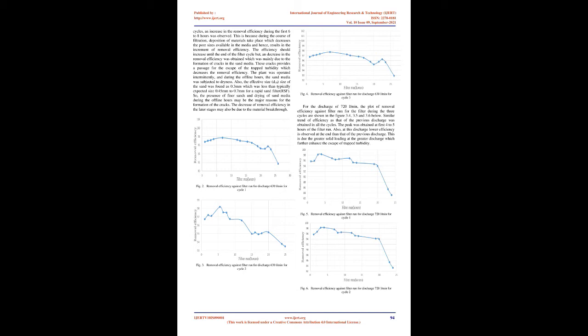Flocculator. A baffled type hydraulic mixing flocculator has been used. At the beginning of the flocculator, a separate chamber for the mixing of alum is provided. As the coagulant is added to the water, the colloidal particles are destabilized and they start to aggregate.